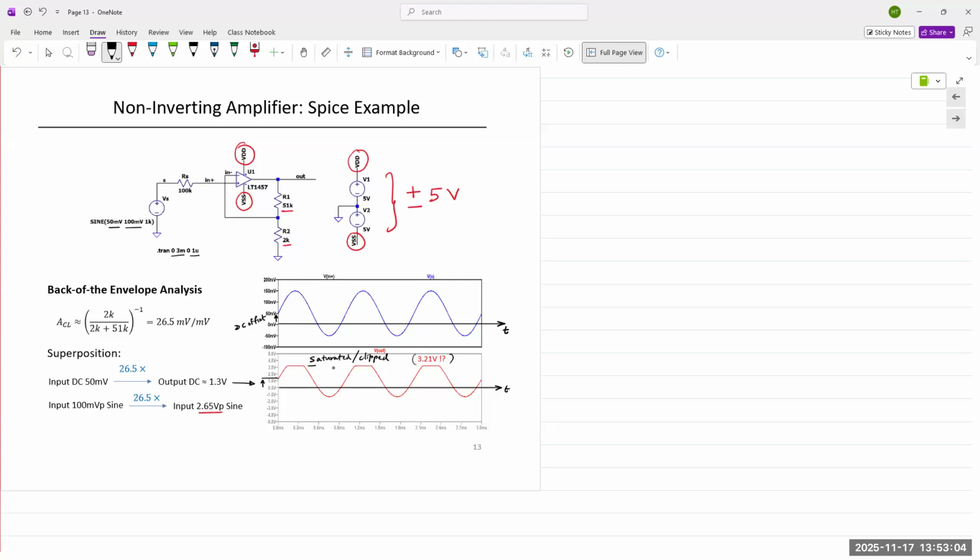The question being asked is about this RS resistance, and why is it large? Oh, here, RS. That's a random value, just to show that it's a very large resistance and a very small current is actually going in. If you make it very small, then chances are a lot of the input voltage could drop across that resistor.